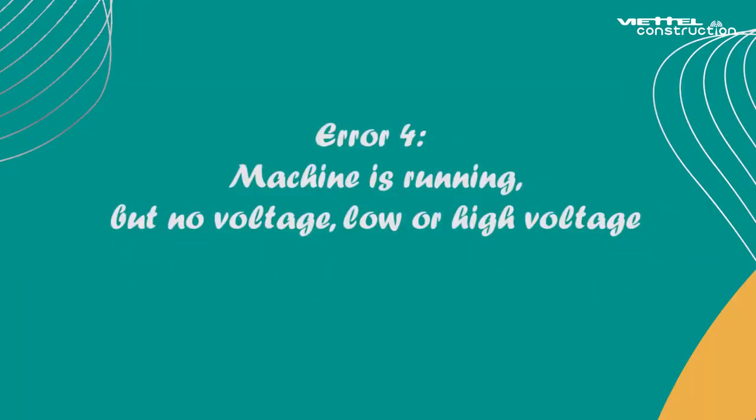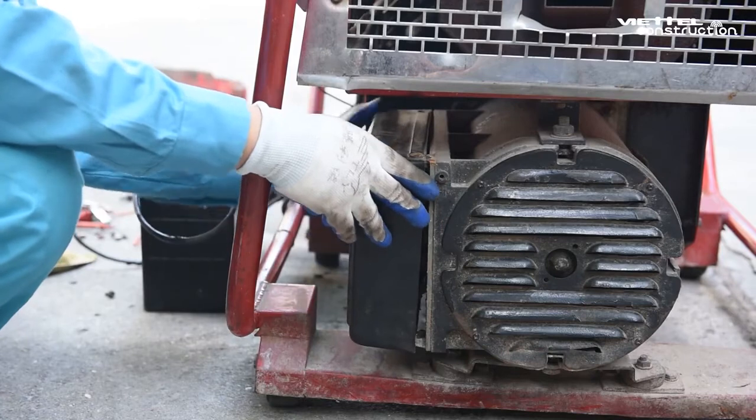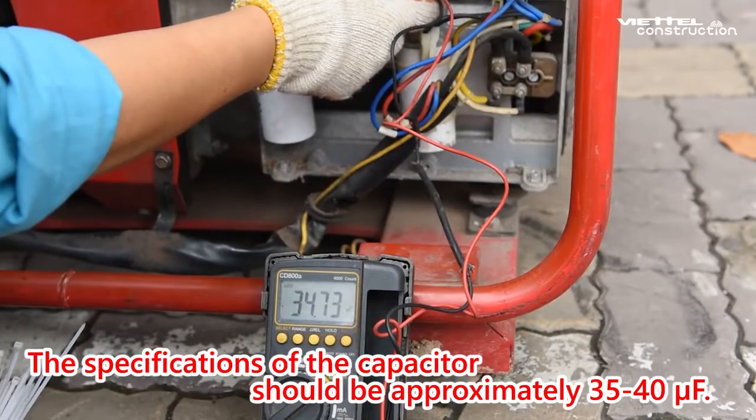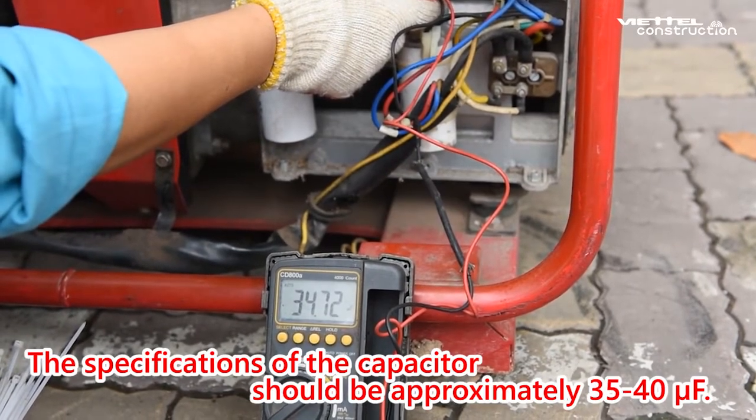Error 4. Machine is running, but no voltage, low or high voltage. Remove the lid of the electrical box. Check and clean the capacitor connection points. Conduct measurement of capacitor parameters. The index should reach approximately 35 to 40 microfarads.